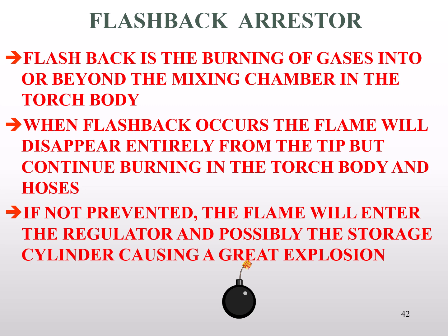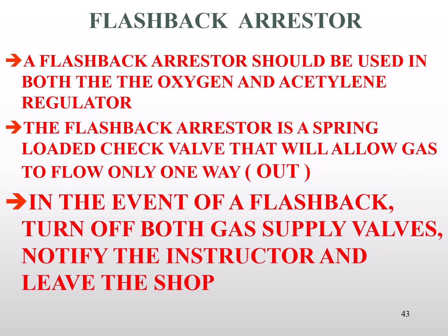It's dangerous. However, flashback arresters are used. It prevents the reverse burning of those gases into that system. All of our equipment has flashback arresters installed. However, make sure you contact me if you feel that a flashback has occurred. If your equipment has a flashback and you think you're experiencing one, turn the main valves off. Come immediately to me in the lab and let me know.